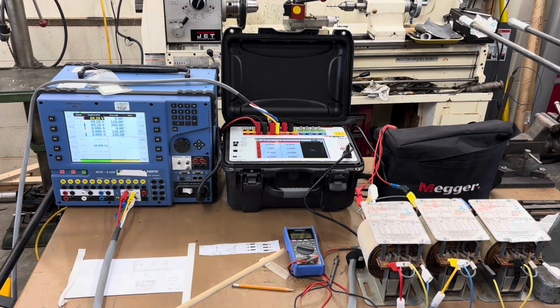and we're going to apply ACB or 132 phase sequence to the same transformer. We're going to witness the phase angle displacement between the primary and the secondary with the phase angle meter, and what you will see is that if you apply a backwards phase sequence to a delta Y transformer, you also invert the lead lag relationship between the primary and the secondary. So if we apply backwards sequence, or 132 ACB, instead of it being a 30 degrees lag on the secondary, it'll be 30 degrees lead.